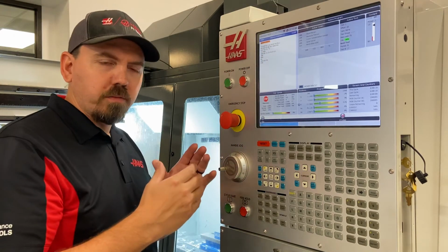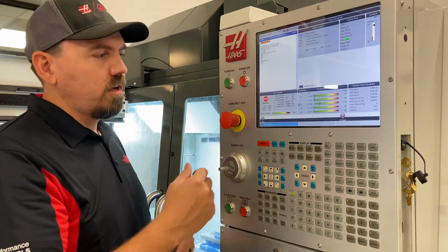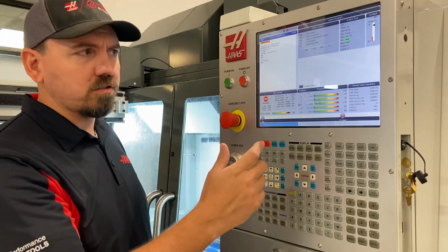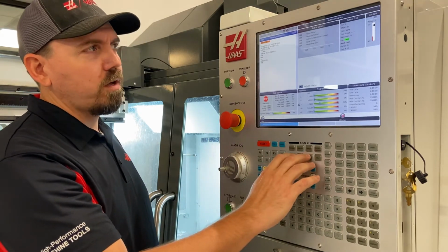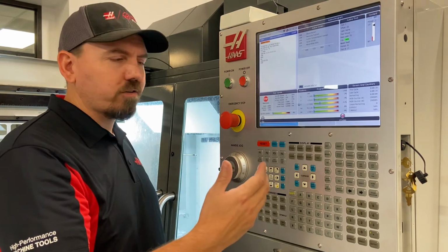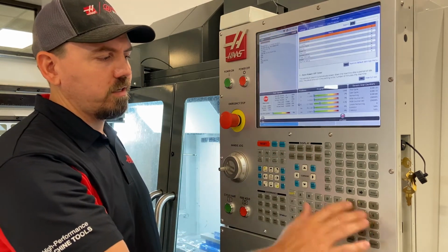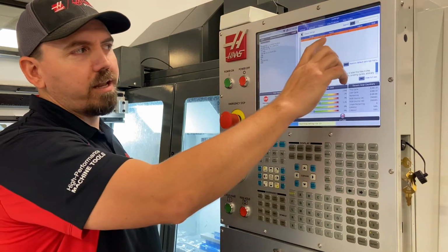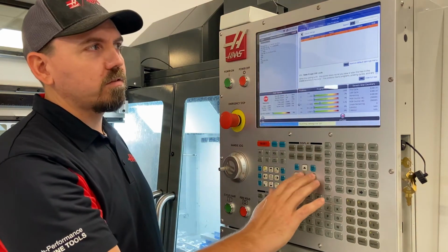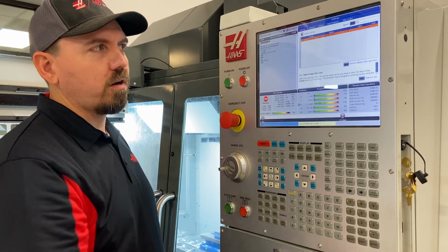We're going to make it do something other than just a tool change. So let's get started. First thing we need to do, because we're going to work in the 9000 macro programs, we need to go to setting 23, and we need to turn the edit lock off. Just cursor over, turn it off, okay?